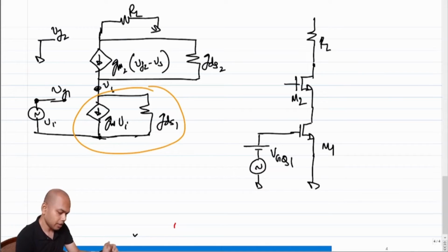So clearly you cannot leave it floating. Can you keep it grounded? I cannot keep it grounded because of what? Because ultimately I need to bias the transistor in such a way that some current flows, right? We need some current, let's say some current I naught, to flow in this stack, right?